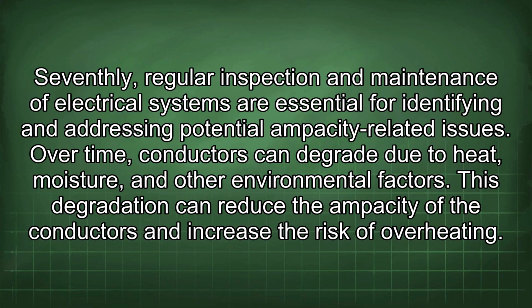increases. Seventhly, regular inspection and maintenance of electrical systems are essential for identifying and addressing potential ampacity-related issues. Over time, conductors can degrade due to heat, moisture, and other environmental factors. This degradation can reduce the ampacity of the conductors and increase the risk of overheating.